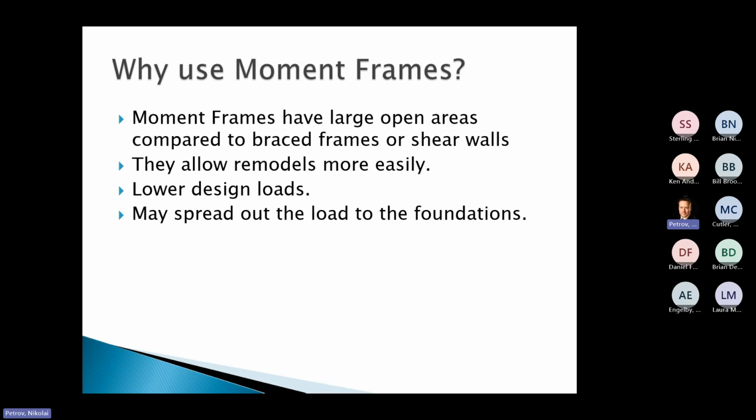Thank you. So why use moment frames in general? I think that those of us, we're all structural engineers, understand why we might use moment frames. The main ways to hold a building up laterally are brace frames, moment frames, and shear walls. It kind of comes down to one of those three things. Moment frames are great because they give you a wide open floor plan and a lot of flexibility.